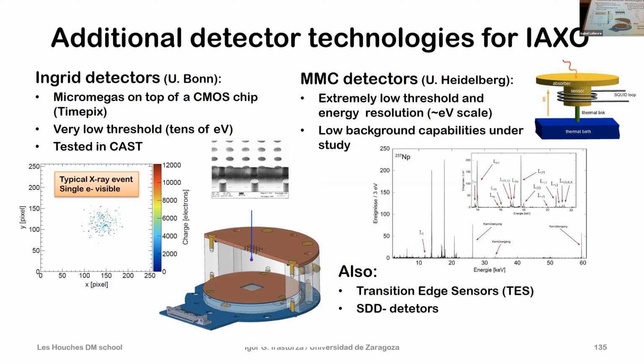In the next layers you can relax the specifications of this lead. It can be more normal lead, because it's blocked by the inner layer, which is clean. But lead is a typical material to shield. Of course, it has to be pure lead.